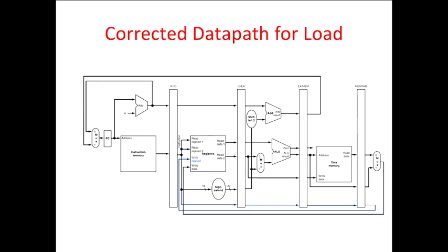How does it know to write back to the register? Like you move the instruction down and then... So remember when we talked about decoding the control signals last lecture, there's a table of, if these bits are in the instruction, this means it's a load, and a load, you can decode to mean it writes the register using the address in the RT field. So all that logic, you kind of replicate in each pipe stage.